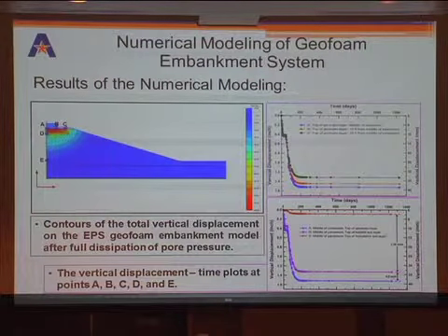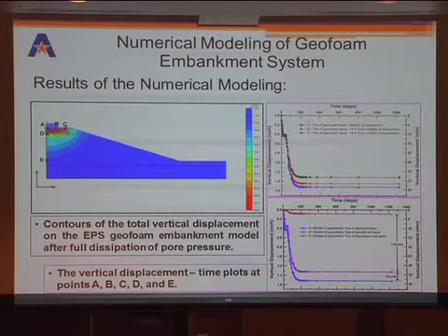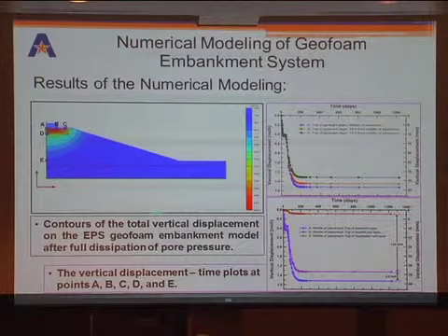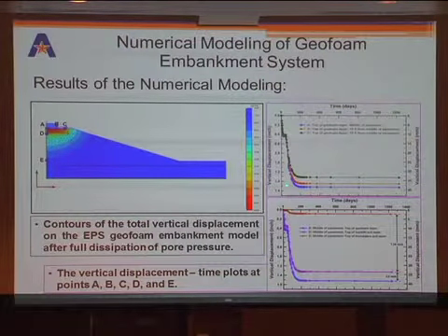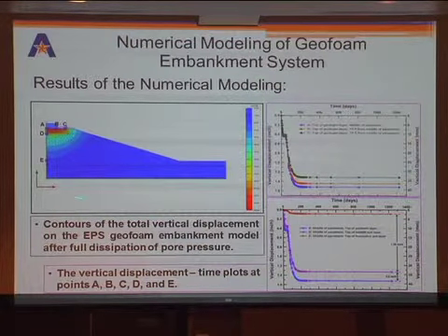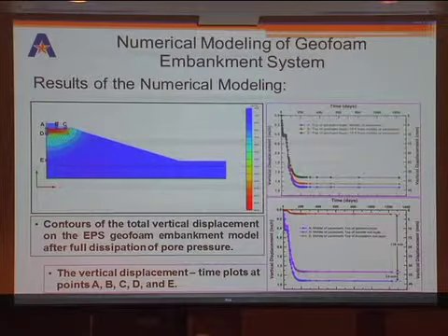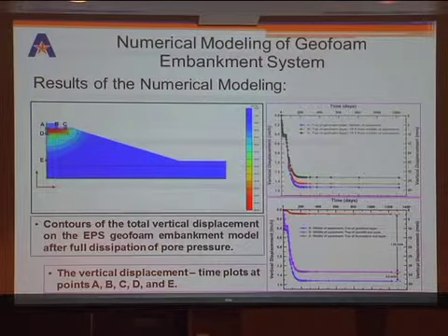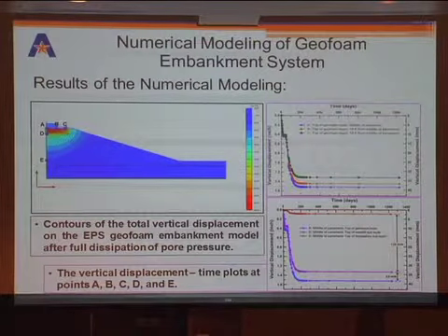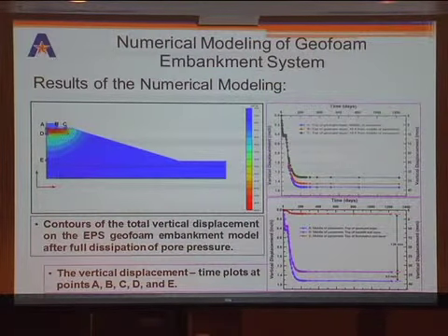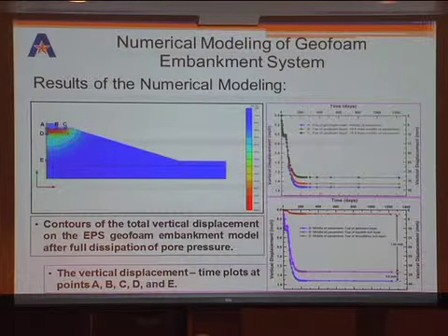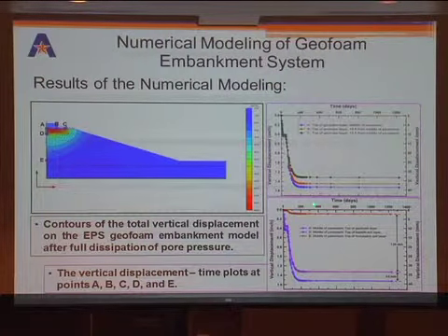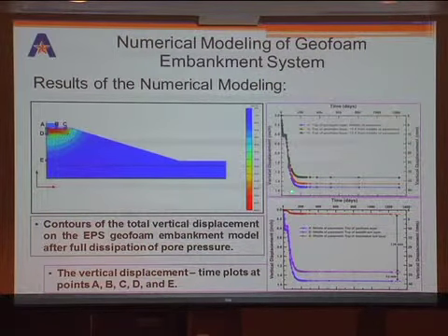So we looked at all our lab data from your materials, including foam. We input everything. And if you look at some of the settlements, what we picked is around 1.6 inches at the surface. So this is the settlements we have collected over the time period. Again, the settlement we collected is using a static loading on the pavement. We did not use a dynamic nature loading. So within a short time frame, we saw that settlement is around 1.6.